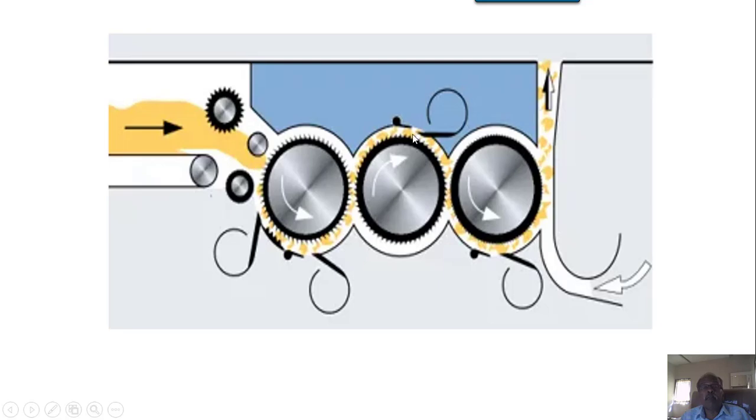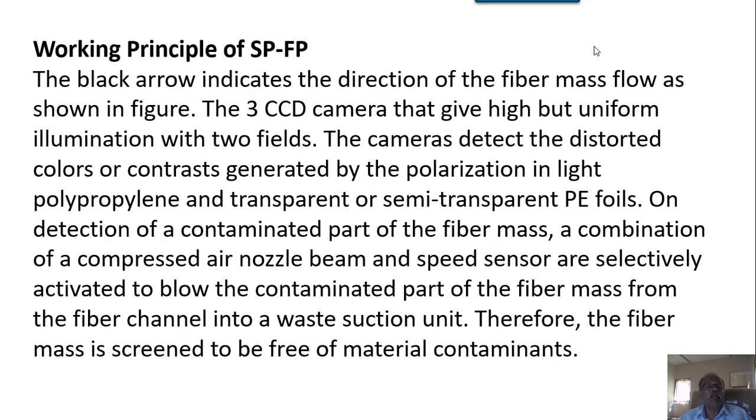So after the intensive treatment, the tuft size has got reduced now, and more or less whatever 40 to 70% cleaning efficiency we had discussed earlier in the modern blow room line, that has been achieved by this stage. Most of the foreign fibers or metals, if at all they were present, are got rid of, and then this reduced tuft size of the cotton will go in the next chamber, next department. So just now I have mentioned the working principle of this one.